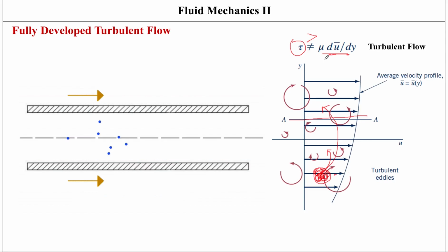I'm just going to restrict myself to giving you this information: this random momentum transfer that is happening here is based on u dash. This is based on the x component of the velocity in conjunction with the y component of the velocity, let's say, because this is interacting with the shear force, and this is interacting with the rate of mass transfer that is happening across this plane, sorry.